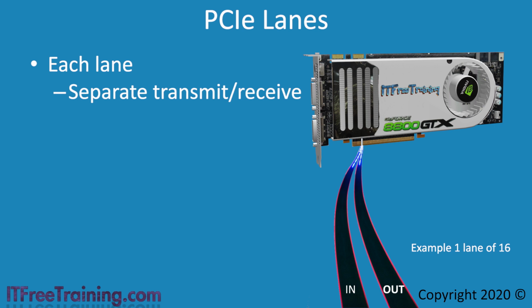The same applies with the bus. You need to wait for all the electricity on the bus to subside before it can be reversed. PCI Express also uses two wires for data. Data is transmitted using differential signaling. This essentially means a 1 or a 0 is determined by looking at the differences between the two wires.